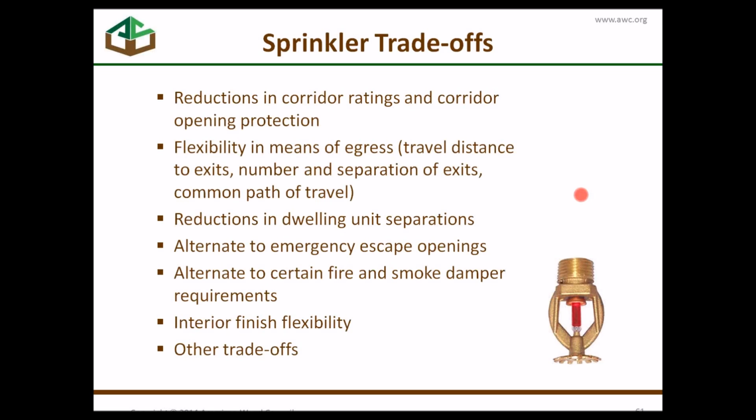The code has many trade-offs for sprinklers, including reductions in corridor ratings and corridor opening protection. You get a lot of flexibility in means of egress. There are reductions in dwelling unit separations and so forth. The list is here; this is only mentioning a few.